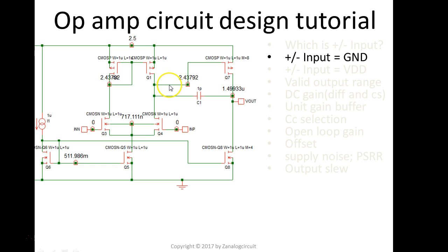Or in some cases, this voltage is really close to the rail here, which means this one's off. So just watch out, a lot of times simulation is right, but once in a while it could throw you off. Just remember that when a node is a high impedance node, when this side is off and this side is off, its voltage is undecided.